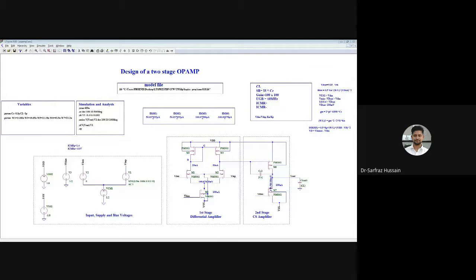So basically I6 upon I4 will give us S6 upon S4. I6 upon I4 will give us the value of the transistor size, or the dimension. We can use the word D for dimension, so the dimension of M6 upon M4. We already know the value of M4, and we know the values of I6 and I4, so these two current values we already know. We know the transistor size of M4, so we can easily calculate the value of M6.